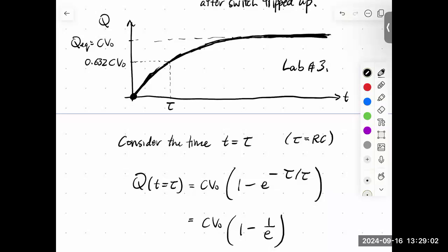That's useful information because if you want to fully charge a capacitor using an RC circuit and a battery, which is exactly the situation we're considering here, the time it takes to fully charge is several time constants. So it's typically 3 to 5 time constants you have to wait for your capacitor to fully charge up. And so if your R and C combine to be like a microsecond, then when you close the switch, you wait 3 to 5 microseconds, and then you could be sure that your capacitor is basically close to fully charged.